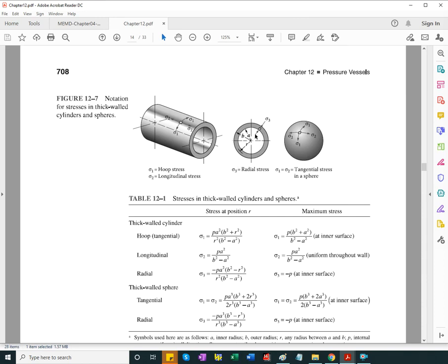And inside pressure is going to act normal to the inside surface and creates a compressive stress to an element that's to the inside. On the outside, it's atmospheric pressure that's assumed to be 0. Okay, so again, read carefully what A and B are, identify them for your problem. There will be essentially inner radius and outer radius.